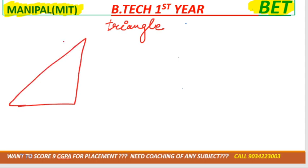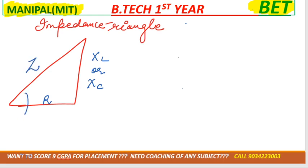Basically we'll have three triangles. One of the triangles is the impedance triangle. In this one the base is the resistance R, the perpendicular is the inductor's reactance XL, and the hypotenuse is the impedance Z. So this is the impedance triangle. Now if I say, can you tell me the sin phi value, cos phi value and tan phi value? Will you be able to tell me?